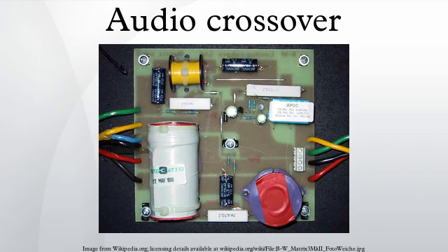A fourth-order crossover with a 6 dB crossover point and flat summing is also known as a Linkwitz-Riley crossover, and can be constructed in active form by cascading two second-order Butterworth filter sections. The output signals of this crossover order are in phase, thus avoiding partial phase inversion if the crossover band passes are electrically summed, as they would be within the output stage of a multi-band compressor.